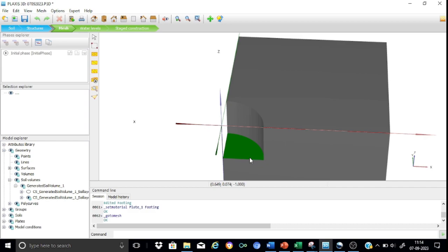So we need to mesh this a little bit finer. Then we can adopt a medium coarse mesh for the balance portion. Let's select it. If you select it, you will find that there's a fineness factor of 0.5. I want to keep it much finer, say 0.25. So we can refine the mesh over here, and you can just press it. Now you can see that there's a 0.35. Again press it, and you will find that it's 0.25. That's okay for us.